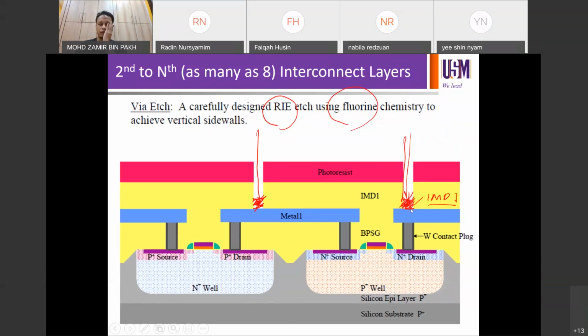So normally when you finish every single process that you do here, you need to do visual inspection in the fab. By Leica microscope, you need to put the wafers after the etching process to be inspected, then you can see whether you still have IMD residue or defects or particles. Then only you proceed with the next step. So it has to end with a visual inspection process after every single processing.